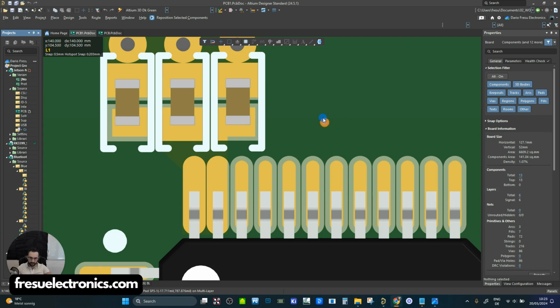So this will become important because the inductance is related to the package, but then also it is related to the inductance of the traces that we have. So the way you're going to route the capacitors to the pin that they are feeding is very important as well, because the inductance is dependent on the trace which they are connected to.